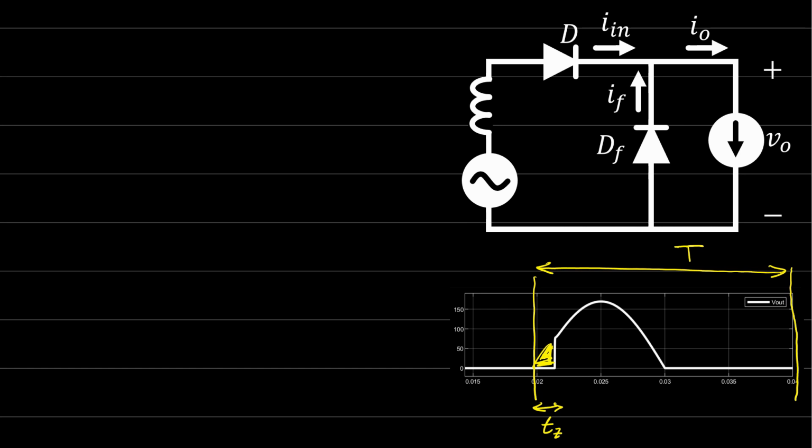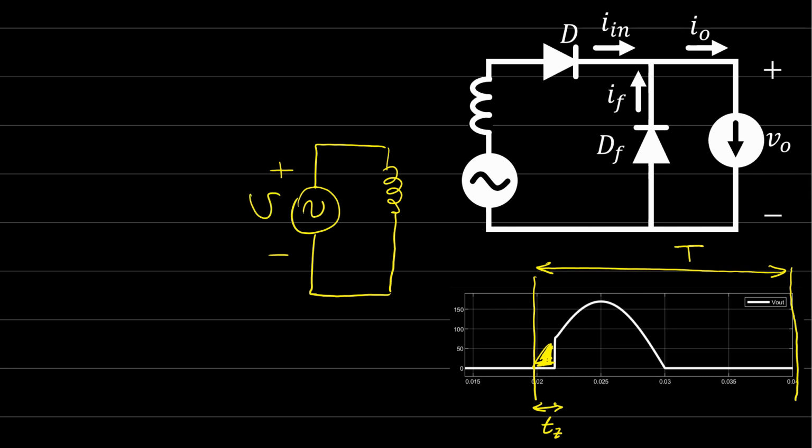We said that you can draw the circuit again here when we have commutation. If we say this is the input voltage, VA or V input for example, the current was flowing in the freewheeling diode first, and then in the commutation the current will start flowing in this direction slowly and slowly. Since the current is increasing in this inductor, the voltage polarity will be something like this. We can say this is L dI by dt.